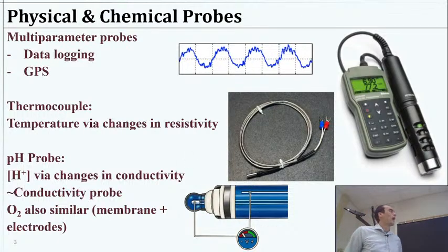Okay, so as you use these in the lab or in the field, keep in mind that your electrical connection is really the important part. So making sure you have batteries and they're not going dead on you is probably going to be important. Making sure that you are taking proper care of the probe itself. pH probes, for example, you might think to yourself, oh, I need to clean this off. I just put it in some dirty water. Let's make sure we clean that off.